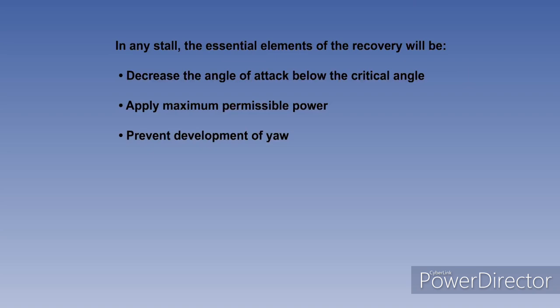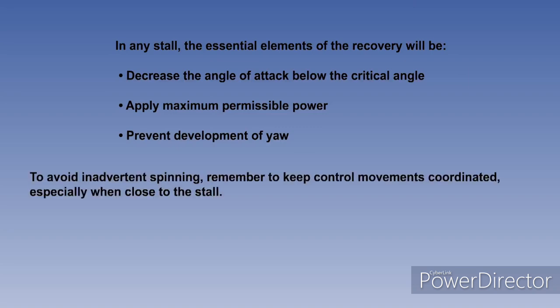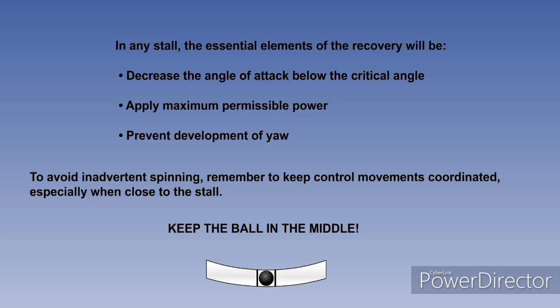Invariably, this will include decreasing the angle of attack below the critical angle to unstall the wings, simultaneously applying maximum permissible power to accelerate and minimize height loss and prevent yaw from developing. At any stage of flight, it is important to fly in balance. But when close to the stall, it is essential to keep control movements coordinated to avoid an inadvertent spin. Remember, keep the ball in the middle.